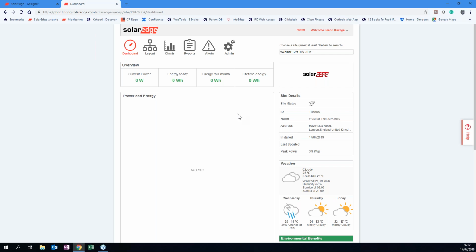Okay, so you've designed it, you've gone all the way through the design with your bill of materials and ended up having a list of components that you need, the angle that you need, what you're going to get as projected earnings, production, and then you're creating the site ready to give to your installer, him or her, just to put it onto the site mapper, scan the barcodes and put the optimizers and panels in the right place and connect it online. So that's all done. Okay, so that's the basic one done.